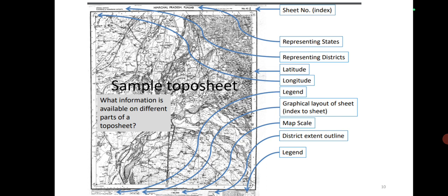So here you can see this representative fraction. As you know, it is a ratio of the length on the map to the actual ground distance. And what is scale, then contour: it is a line connecting points of equal elevation above sea level. Then contour interval, then contour lines are sometimes thickened at regular intervals to make it easier to read. So certain portions will be thick. One contour line will be there, and in order to easily distinguish and identify, certain portions of the contour lines will be made thick. So that we call an index contour.